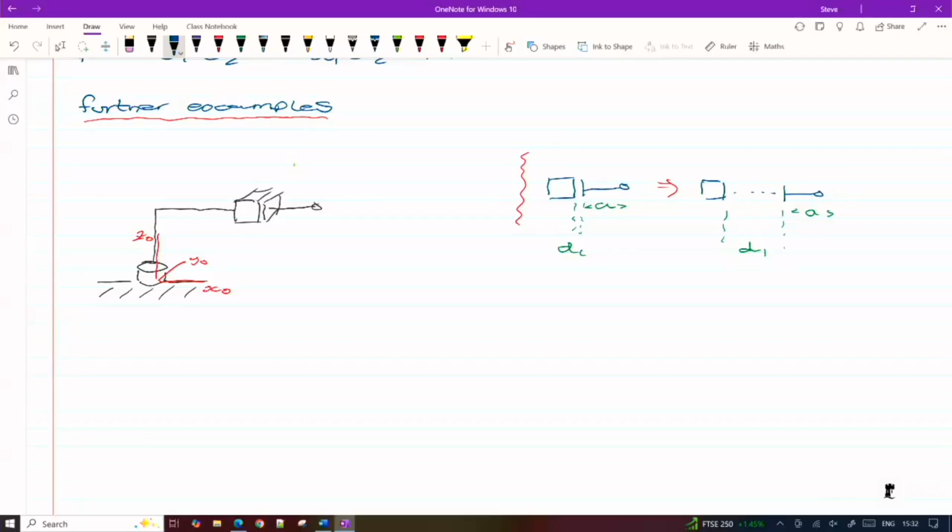So A is always fixed, that's fixed in the mechanical structure of the joint. D is our joint variable for a prismatic joint. So here I've just shown the fully retracted state of the joint and then an extended state of the joint. When you come to, or if you're asked to draw a problem, or if you're presented with a problem, the A's may be 0, or if there are arrays involved that you put into your drawing, you can say, for this answer, I'm going to consider the A's to be 0. Okay? And that will just simplify your solution a little bit.